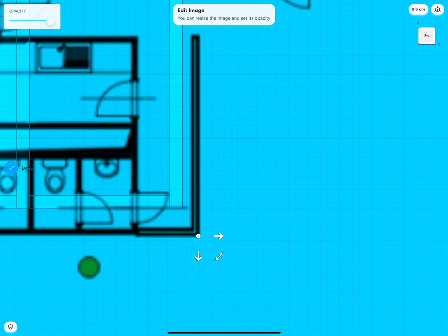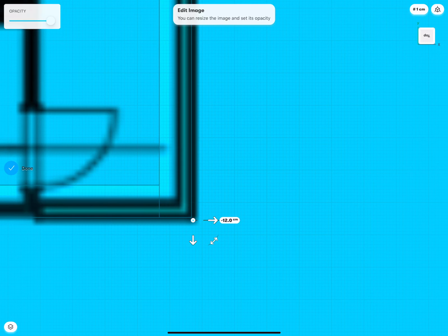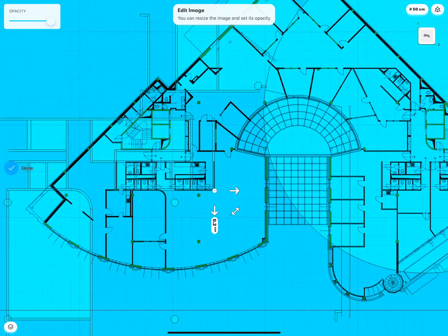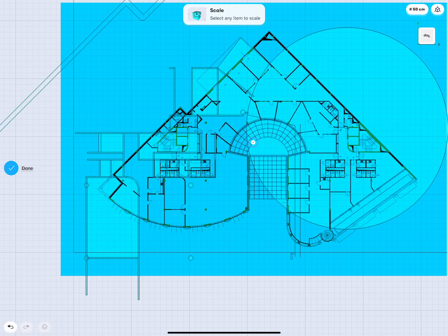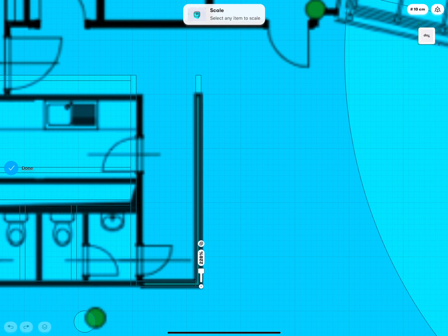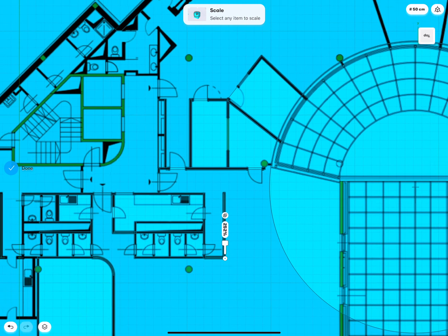You see I'm positioning the move widget right at this corner, so I can line up my DWG, roughly centered, onto the line of the imported PDF or image. Very good. Now with this positioned, I can go to Translate and Scale, reposition that widget for the scale center right at this corner again, and then simply scale this up until, as you can see, everything starts to overlap a little bit.